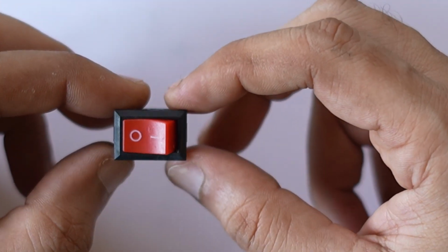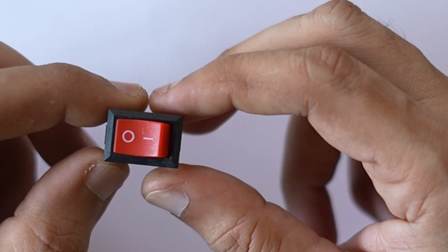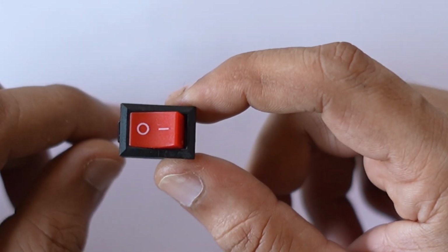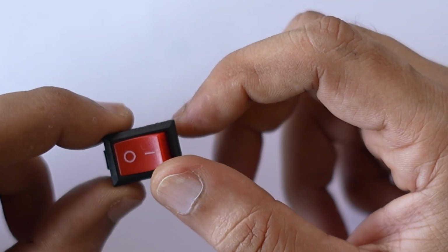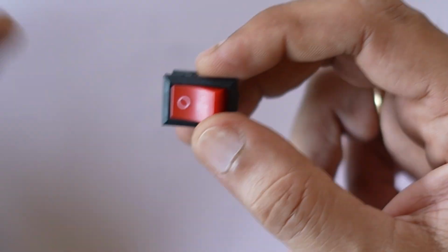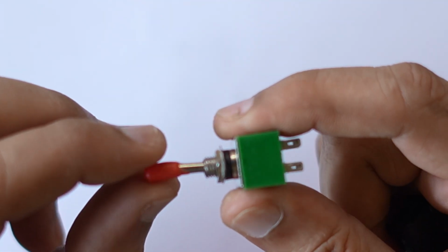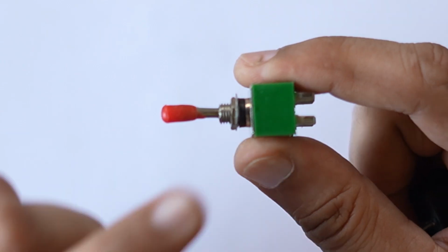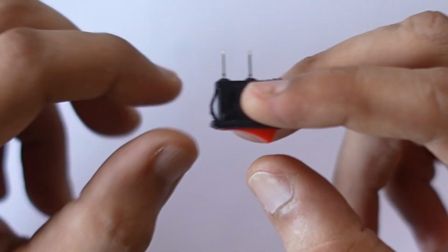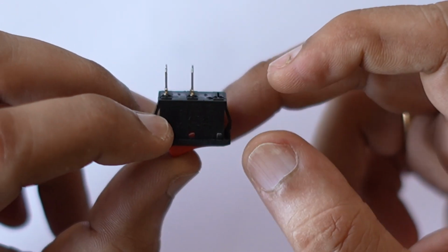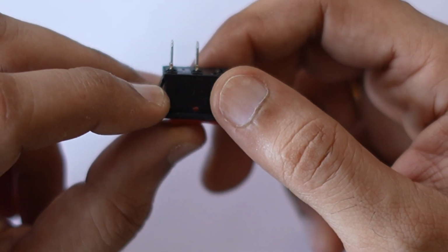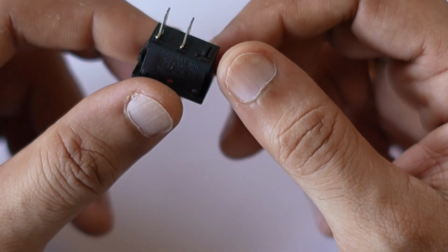This one that I'm holding in my hand now is what's known as a rocker switch because it rocks between the on position and the off position. And you'll find this quite often in many electronic instruments where it is used to turn on or off the device. Toggle switches are usually used for selecting functions. So you have one function and a second function, and you do that using toggle switches. But a rocker switch is most likely used for turning on and off power, most primarily in high voltage devices, appliances that connect to your electrical supply at 230 volts, for example.